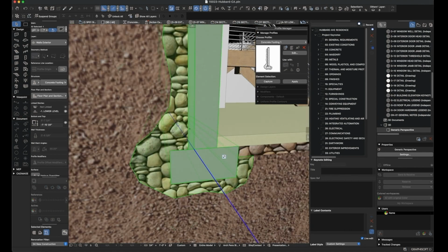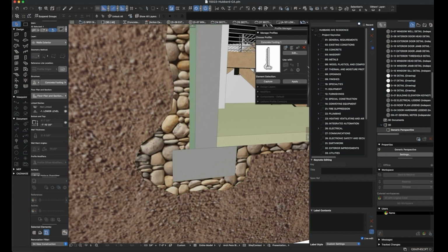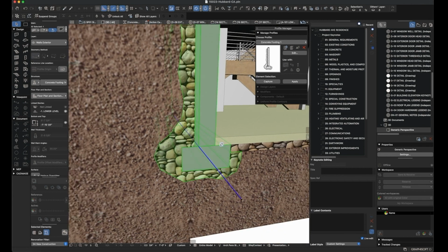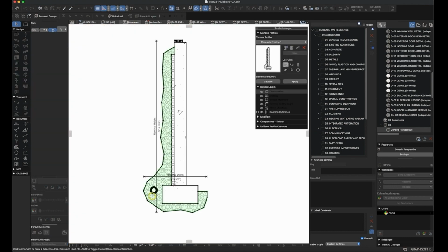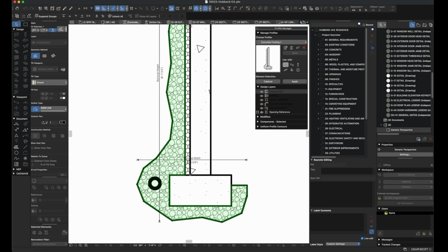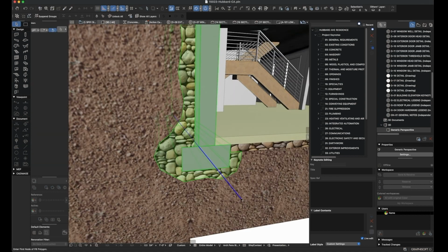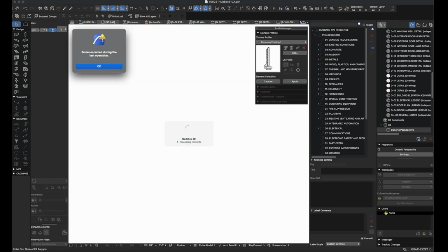Now, you'll see that the pipe is not showing up because what I forgot to do was to subtract that pipe out of the filled region. So let's go back to that, and let's select the gravel chimney, then select the fill tool. Now we're going to hover over the circle with the magic wand, click again, and that will delete that circle area from this gravel area. We're going to hit save, and then go back to the 3D view, and you can see the pipe will now reveal itself.